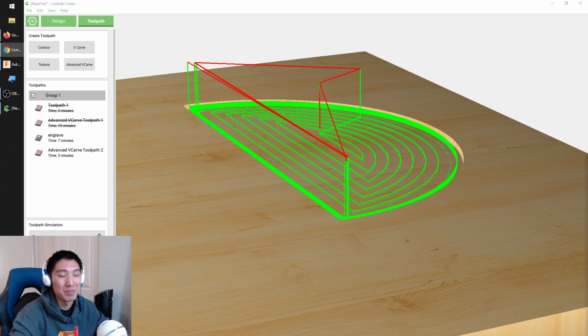Just come up with a basic, simple project, maybe like a sign with a 3D contoured engraving or a topographic carving. Work from there. Get a nice selection of ball end mills, 1/4 inch for larger round dished bowl shapes, smaller ones if you want to do the topographic carvings. Really open-ended question, but if you throw an example, I'll try and address it.